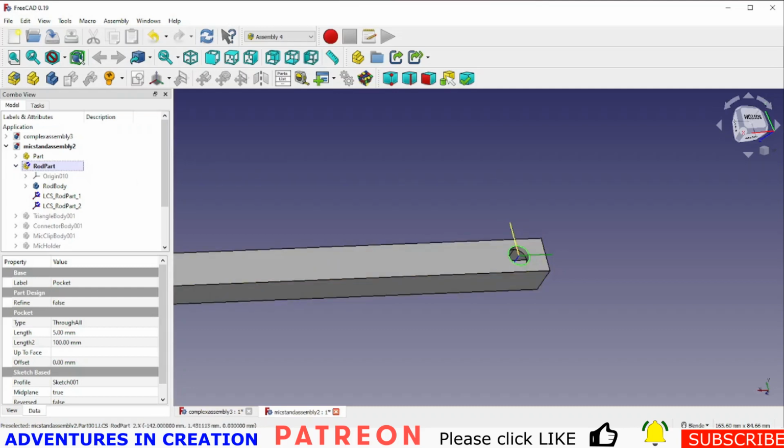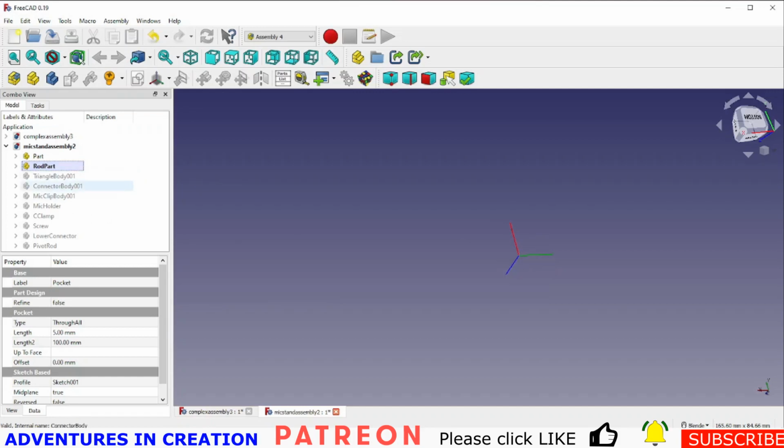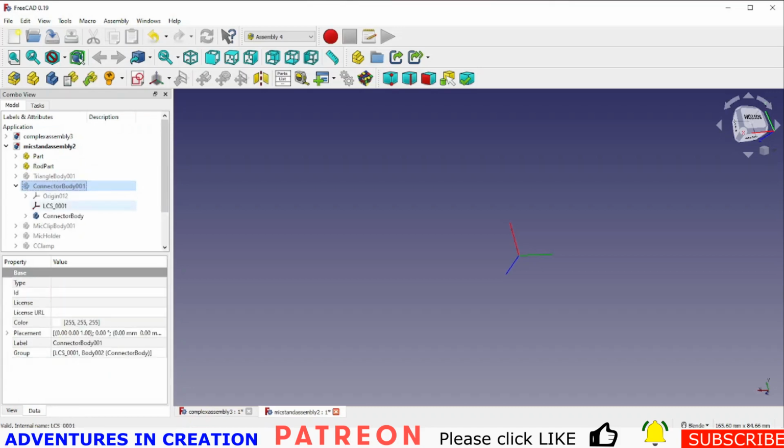Of course, if I put this in on its own, there's nothing else in there. But what I can do is make this LCS line up with the LCS of the parent part. So I'm going to do that. I'm going to go into the connector body, I think is the next one I want. So I'm going to turn off this part just by hitting the space bar. And then I'm going to go into the connector body part. Turn that on. Hit this button so I can see what it is. Yeah, that's the piece I need.